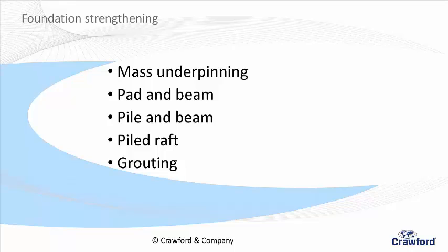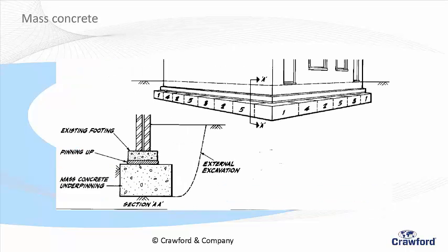So I've got a house, it's subsided, I need to underpin it. I don't go and just dig a whole area, do I, and underpin it because the house is not covered. So I do it in sections. Yeah? And the sections are going to be very strategic in that if I do the number ones on one day, I don't do number 5 the next day, which is next to number 1. Because as soon as I dig down to number 5, number 1 is still setting.